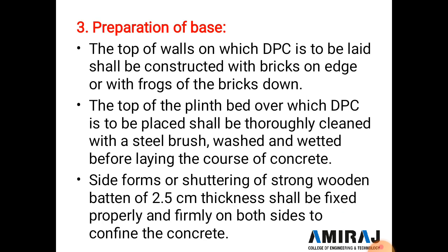Now the third specification is the preparation of the base. So here the top of the wall on which DPC is to be laid shall be constructed with bricks on edge, or with frog of bricks down. The top of the plinth bed over which DPC is to be placed shall be thoroughly cleaned with a steel brush, or washed with water before laying the course of concrete.